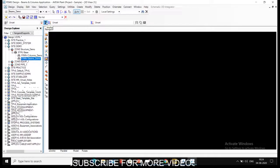Now there are two points with the structure. One is a structure, a profile, C shape, I section, square section, a lot of sections are available with the structure. And second is points. Those are end points, called node points. AVEVA PDMS basically works on the node points of the structure. So you can store all these things into one framework.